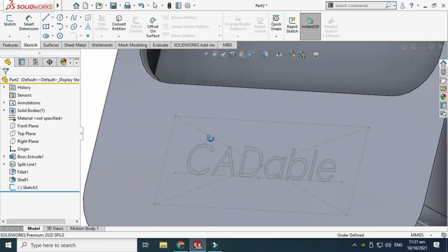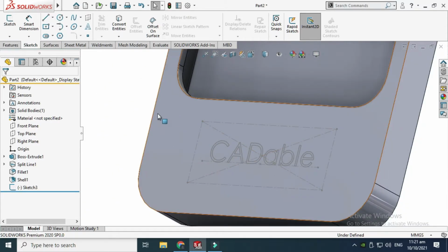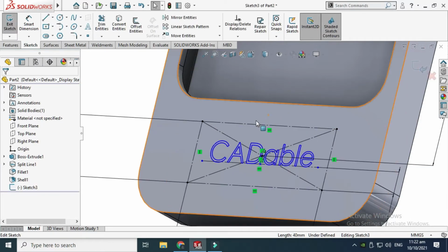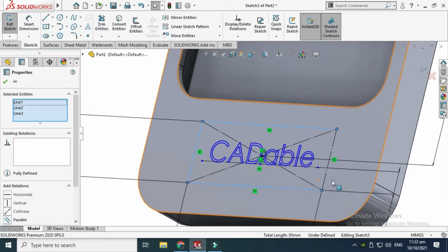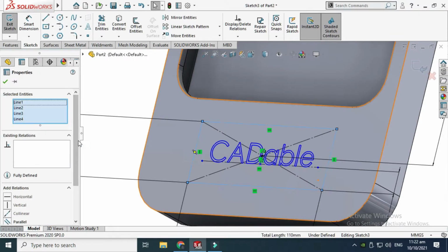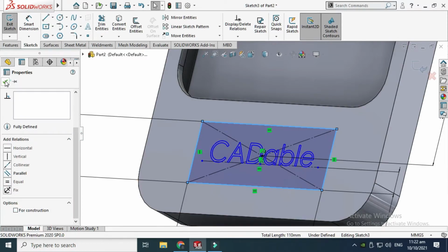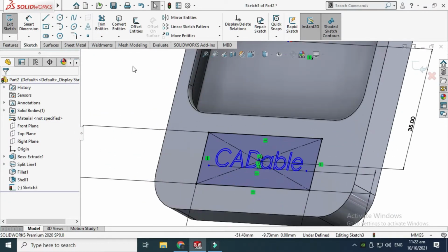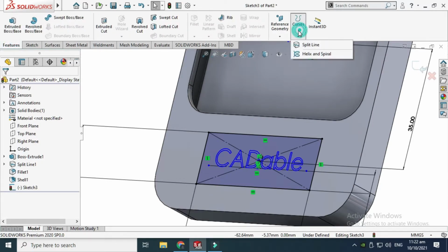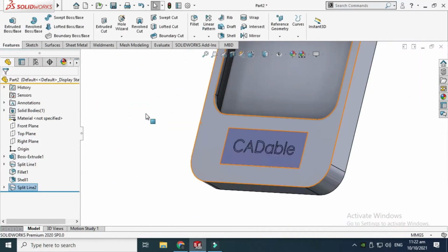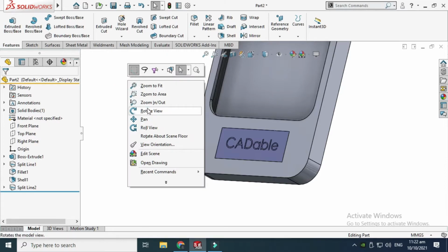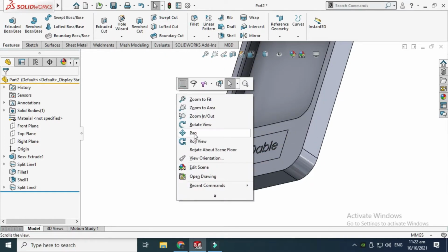sketch, right? Next I'll go to the split tool again, and I'll split that geometry. In fact, just go back in, and I'll make this, let's say, non-construction, because I need that geometry, and you can uncheck this box. Okay, so next I'll go to features, curves again, split line, and this time I'll select this feature and select OK.